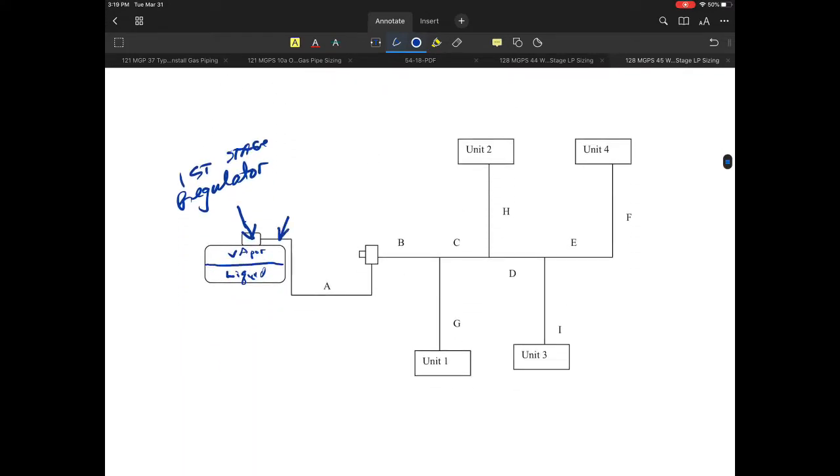Most of the time, that's something that we don't generally have to deal a lot with, but I would generally expect the outlet pressure of that to be approximately about 10 psi. I've heard of numbers being 5 psi on some systems, but I think it's way more typical to see it at 10 psi coming out of that first stage regulator.